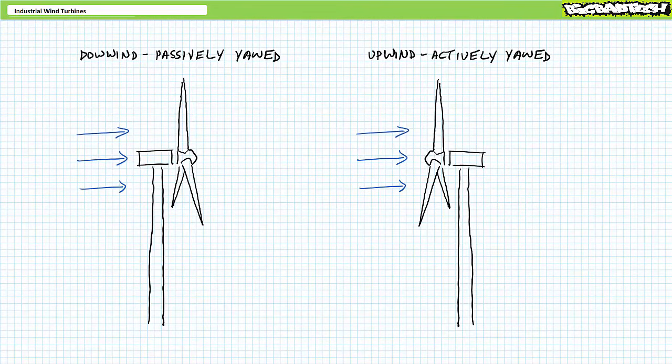A downwind design, as the name implies, lets the wind passively push the rotor mechanism of the wind turbine downwind of the tower as wind would unfurl a flag from a pole. While this passive orientation mechanism is admittedly inexpensive, it's not super ideal, since anytime a turning blade enters the obstructed space behind the tower, it encounters turbulence in the wind shadow of the tower, and sometimes it emits an undesirable popping noise. In fact, a lot of the complaints about wind turbine noise reference these old-school wind turbines.